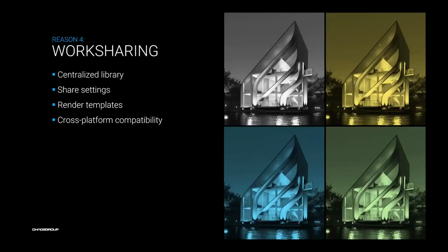With regards to the cross-platform compatibility, the format of the V-Ray materials is called VRMAT. The same material format is used in V-Ray SketchUp and V-Ray Rhino, so no matter which one of those you have, or all of them, you can share your V-Ray materials across the 3 platforms. Furthermore, the VRMAT materials are supported in V-Ray 3ds Max as well. You can export VRMAT materials from 3ds Max.